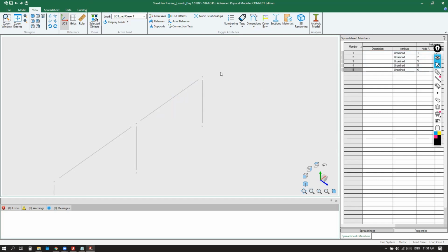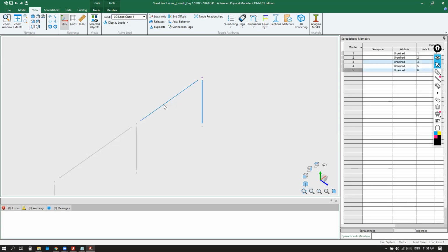In AutoCAD, Roslyn, as you know, if we select from right to left, everything that touches this window will be selected, correct? Like AutoCAD. For example, here I have this node, which is exactly inside the window, and also this column and beam, which touch the window. So if I release, these three elements will be selected.